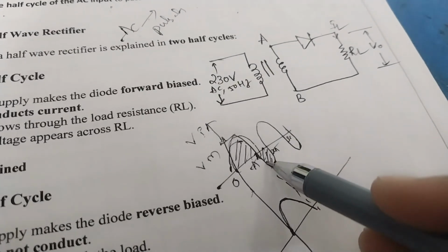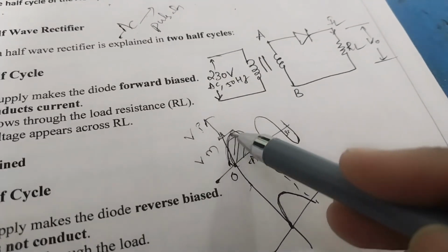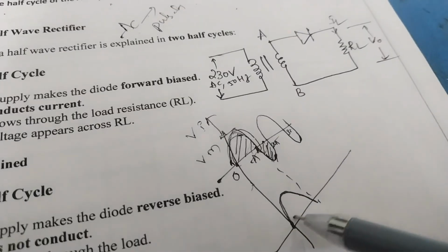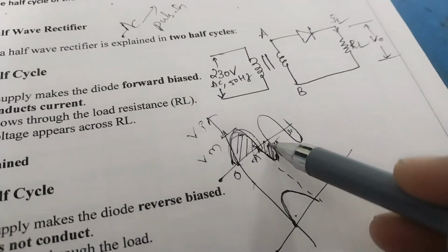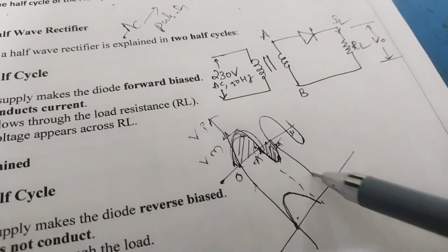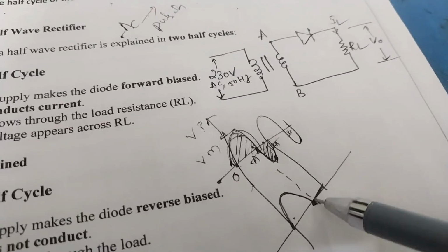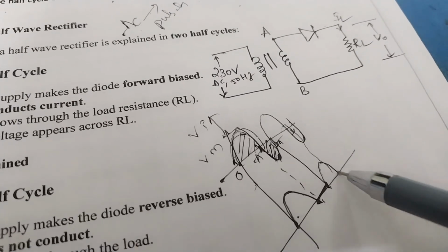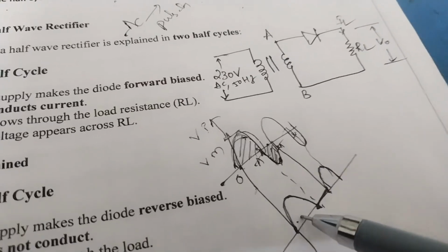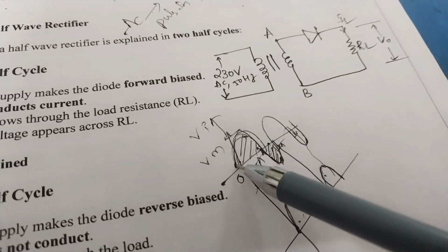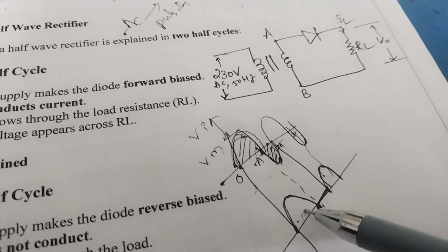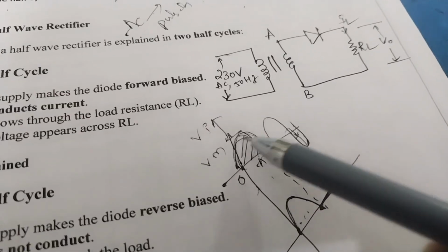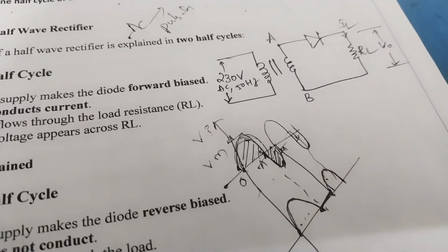That means it does not allow the negative half. Whenever the negative half cycle comes, it simply blocks the negative half. Then we don't get any output voltage in the negative half. And again in the positive half, we get the output like this. So here it is the pulsating DC, it converts AC to pulsating DC, which allows only 1/2 cycle of the AC input waveform.